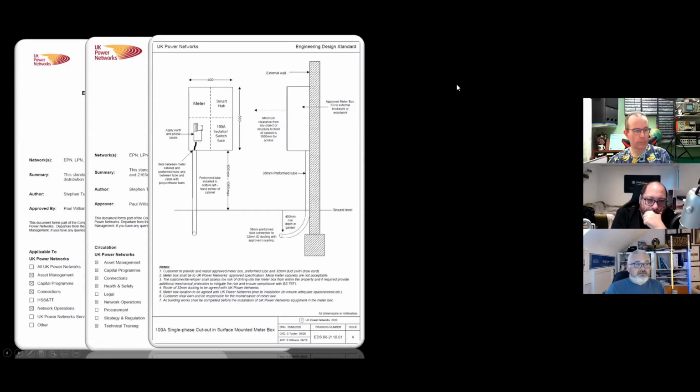The fact of the matter is these smart hubs, they transmit at quite high frequencies. You put a little small EV, type A RCD or type B RCD. Have you done the due diligence? Have you actually said, oh, well, the emissions from that won't affect that? We've seen videos online of people's RCDs tripping out when they put radios up near them. They can be affected. It's electronics. You don't do it. You do not put these boards in. And we've ranted about this.